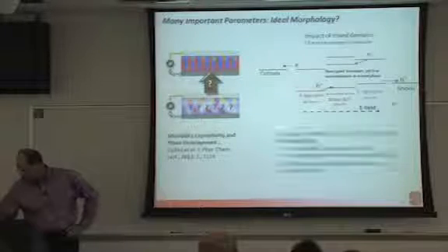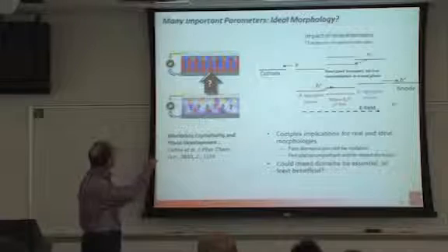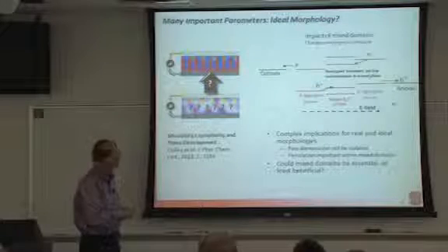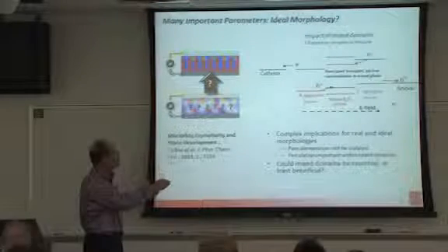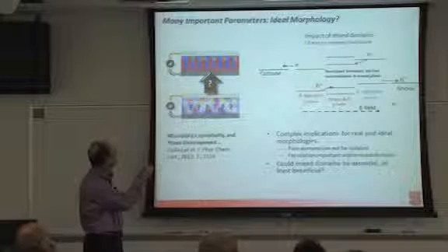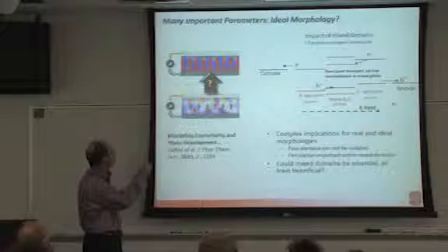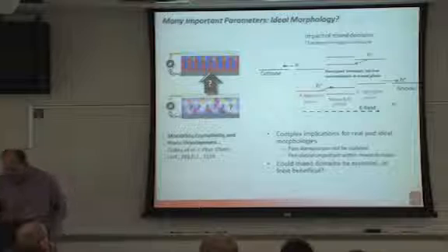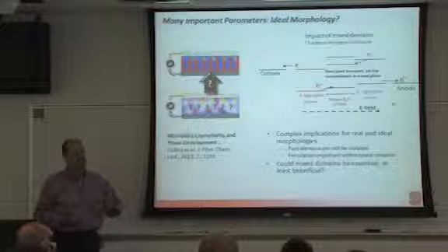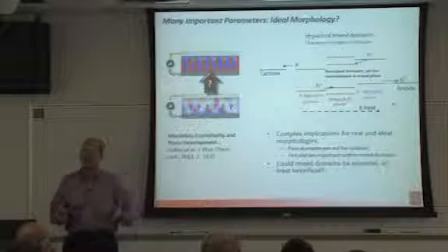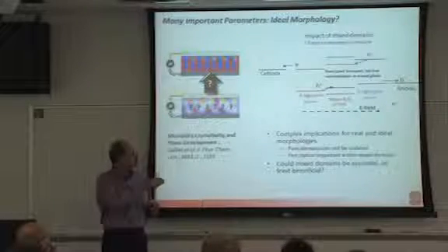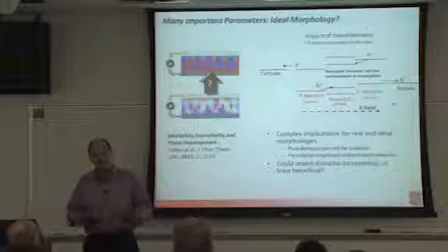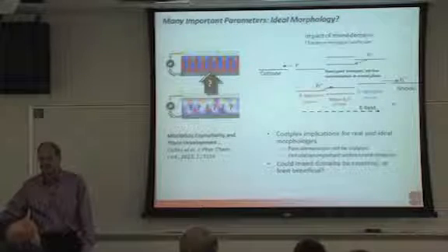But basically there are implications here that if I were to, let's say, just have a mixed phase in between the red and the blue here, make that purple, okay? That would work very well for absorption in the mixed phase, but it wouldn't work very well for absorption in the red phase unless I had good charge transport in the mixed phase. So I have to engineer that transport, and we have a couple of studies now that show, and I will allude to that later, that if, for example, the fullerene concentration in the mixed phase is too low, then you lose the charge transport in that domain and the device suffers. So